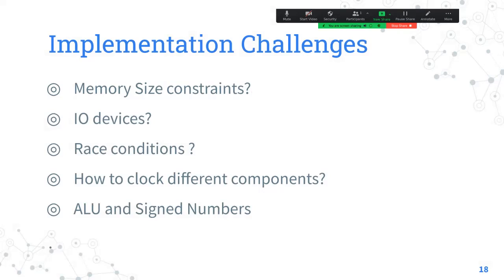The difference is this: in a block RAM, the reading is clocked. The writing is always clocked. When you say write this value, the write will not happen directly. You have to clock it, and only at that clock edge do you write that value to this particular location. So a write is always clocked. But depending on whether the read is clocked or not, you will be able to use block RAM.